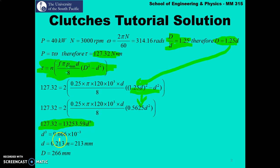D cubed is nothing but 9.606 times 10 power of negative 3. Solving for your d, which is your inner diameter, equates to 213 mm. And once we have this, your outer diameter is simply 1.25 times your inner diameter. So 213 times 1.25, you get your outer diameter to be 266 mm.